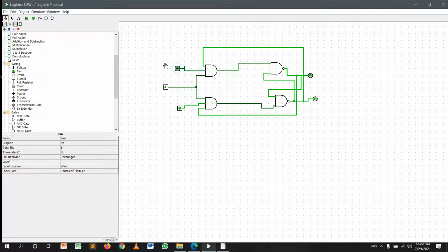When I change those two values, you see the output. Those two inputs 1 1 do not change, 0 1 does not change, 1 0 does not change. And when those two values are 0 and the clock input is 1, it should not change. Those four situations are memory locations in this circuit.